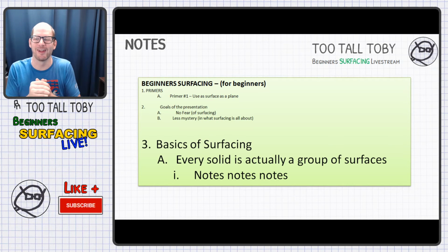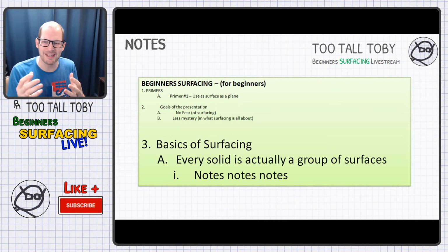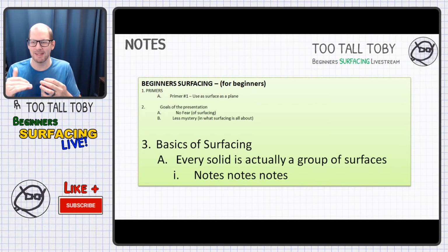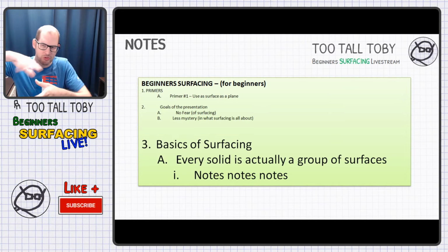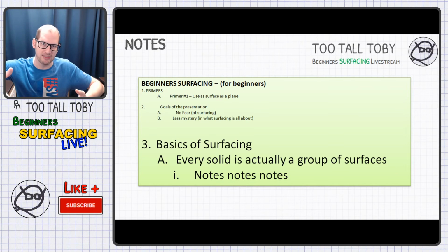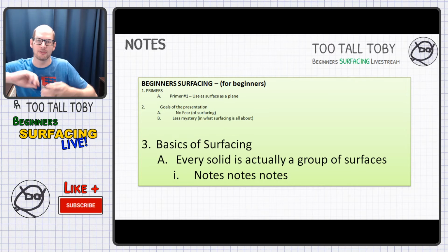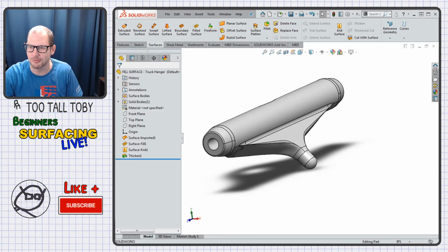I wasn't sure what you wanted to write, but you start out with your surfacing geometry. You take those surfaces, you put them together, you patch, you trim, you knit, and then you thicken all that into a solid. Or in the case of the face shield, you just make one surface, you trim it up so it looks the way that you want it, and then you just add a thickness to it. Instead of trying to sweep that as a solid and then cut it as a solid. I mean, you always run into issues with stuff like that, right?